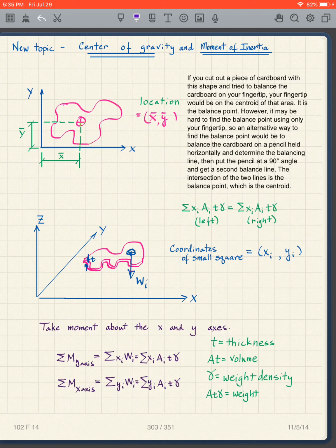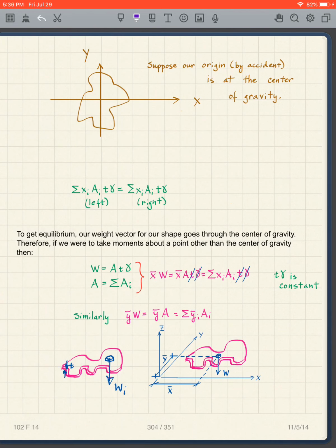Just like we did, if you remember, when we had our triangle here on our beam, and I found the centroid of that triangle using the 1/3, 2/3 rule. Then I put the total load there to find my reactions. So that's one of the uses of the centroid, to be able to put the entire weight at that one centroidal point.